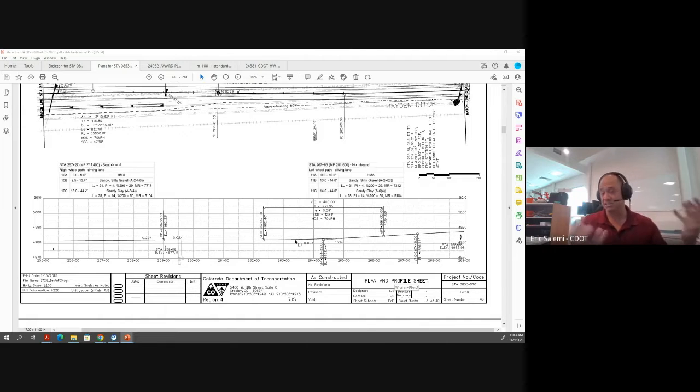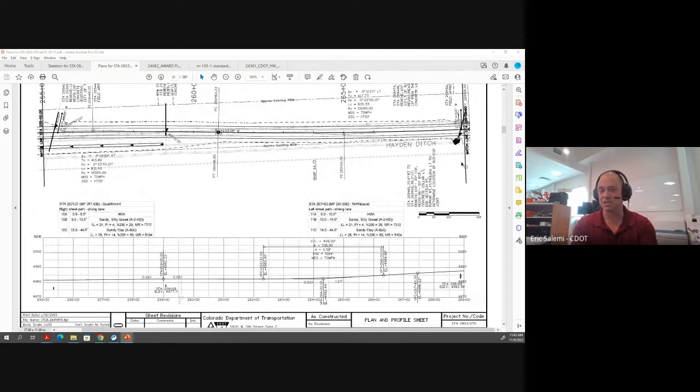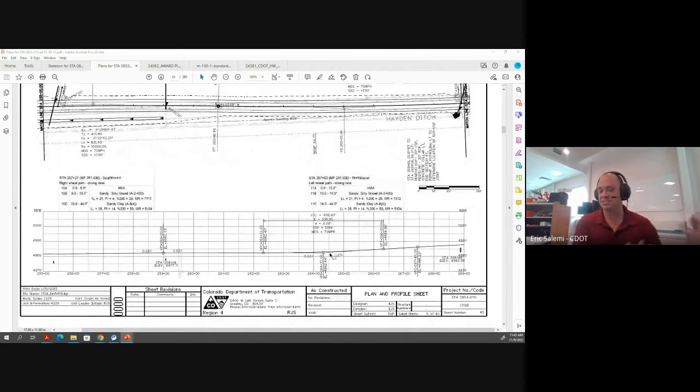And then again, in relation to what Keith had mentioned earlier, this is one of those third locations you're going to see quantities. So again, summary of approximate quantities, your tables, and your notes. As you're reading plans, these things should all match, especially tables in relation to these notes. Stations mentioned in the table should match the stations mentioned in your notes. Quantities mentioned in the table should match the quantities that you're mentioning in the notes. There's that direct one-to-one information. Again, it's just presenting the information in another manner to help clarify what is actually being asked.